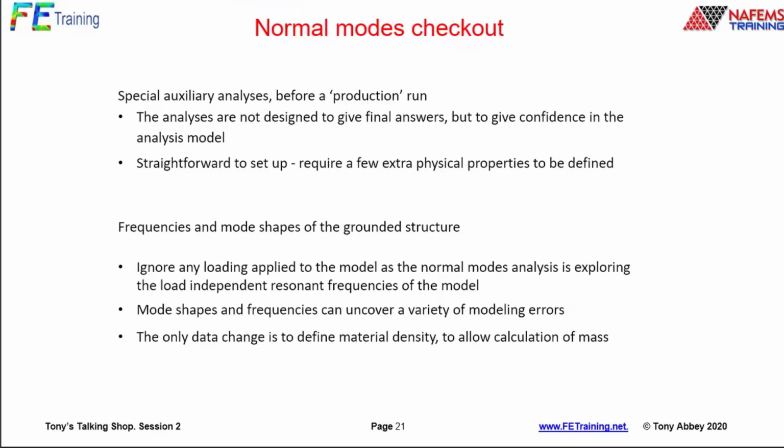Now, frequencies of 0 and clear rigid body modes mean, again, things not connected to the ground. So we're really interested in things flapping around, things badly connected. And it's very, very easy to check to do. If you've never run a normal modes analysis, when you come off this presentation, you get a chance.